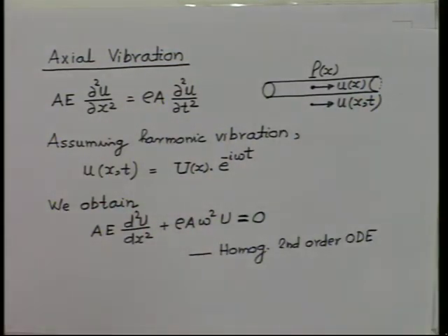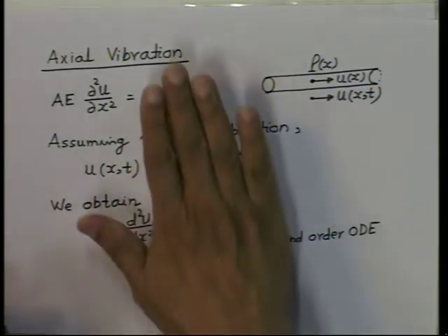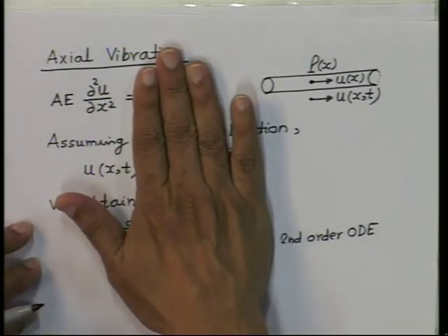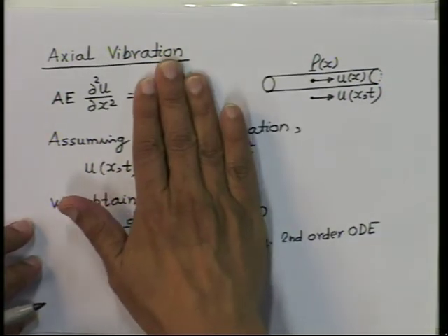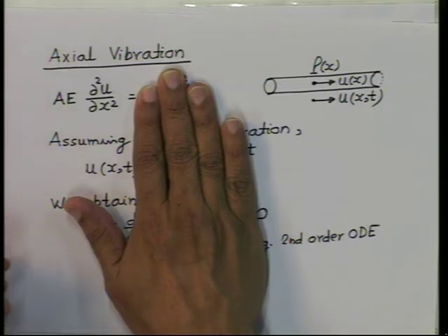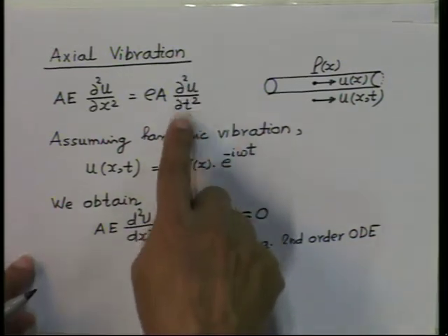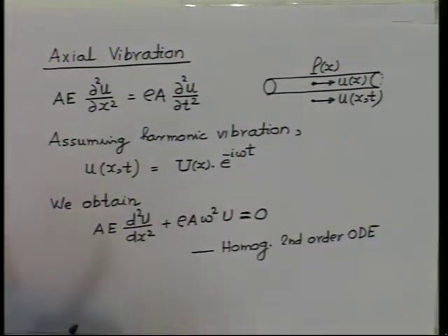The governing equation for axial vibration of a rod is this. This is for axial deformation of a rod. If the right hand side is 0, I have just suppressed it, then this governs the behavior of a rod under action of loads. So, u is the displacement, the deformation, and now the right hand side also has a second derivative with time.